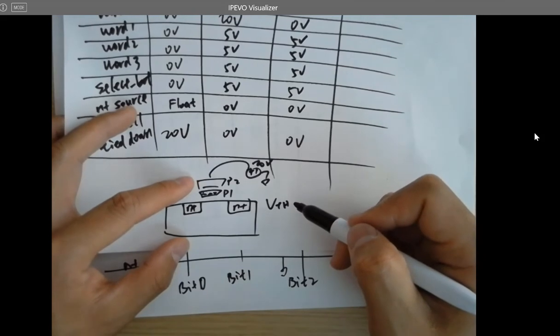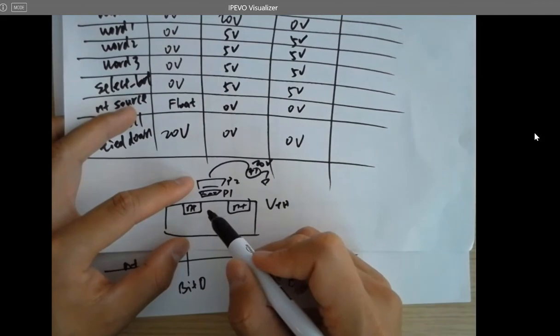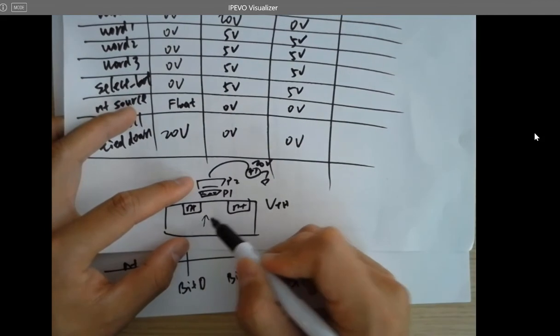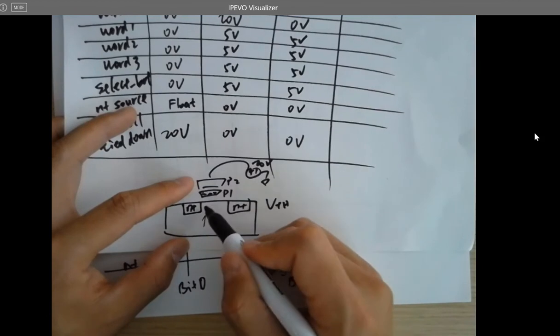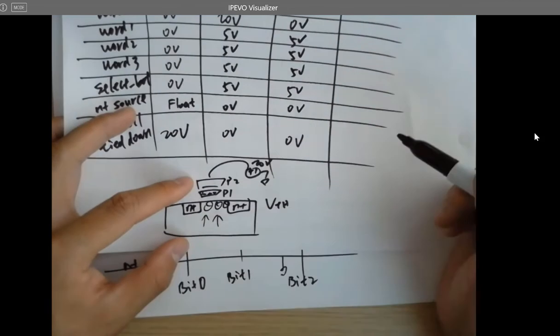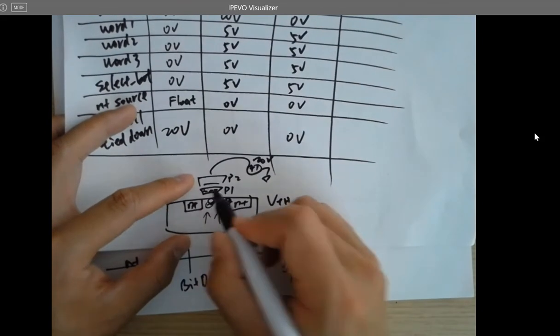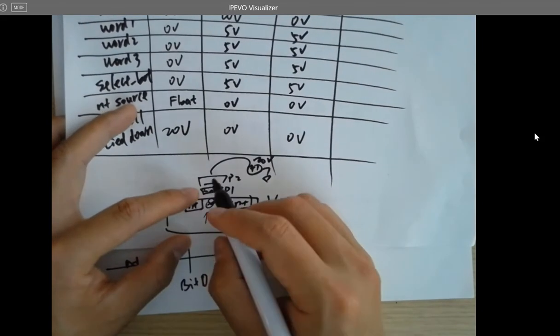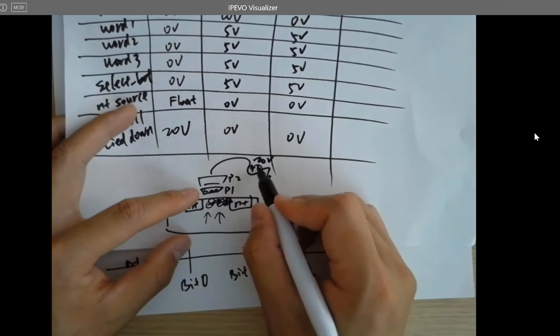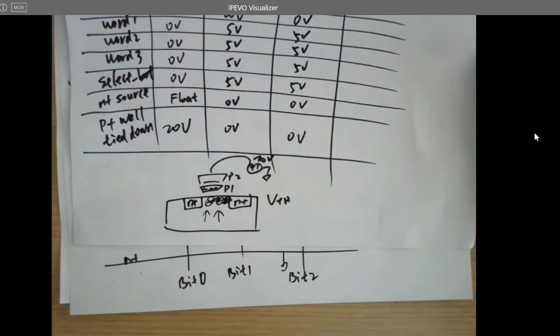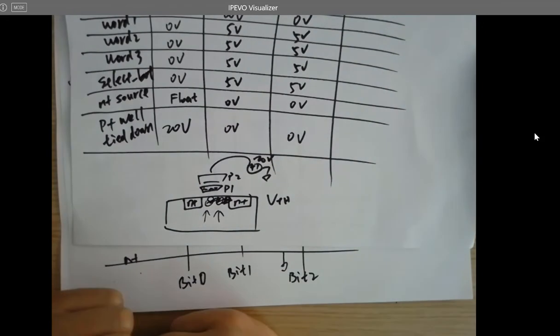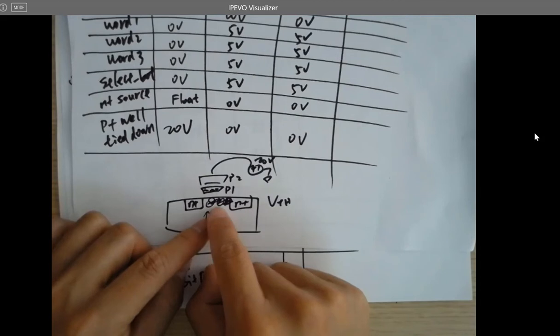Decreasing or increasing? The way to turn on the channel is to invert it, right? So you need a positive voltage to invert the channel so you can turn it on. But now you got something trying to negate the effort of the positive voltage. Whenever you are making it more positive, unfortunately the electrons are trying to negate it back. So that's why you need a higher positive voltage to turn it on. You are trying to invert the channel, not invert P1.